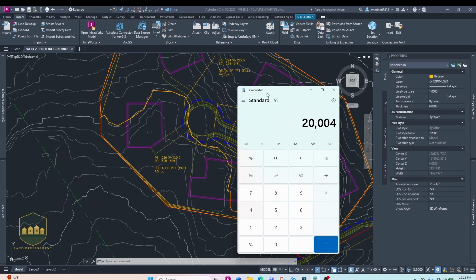So we have 4.75 acres. That's our surface area. And we're trying to get a volume of this. So surface area times depth. So 4.75 acres times 7 feet is 33.25 acre-feet volume of fill. Compared to that, we're going to subtract this other area right here because it's cut. So this is 2 feet of depth times 1.5, which is 3 acre-feet. And we have a total imbalance of 30.25 acre-feet.